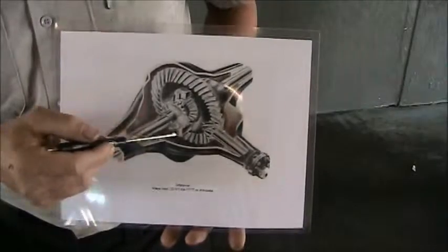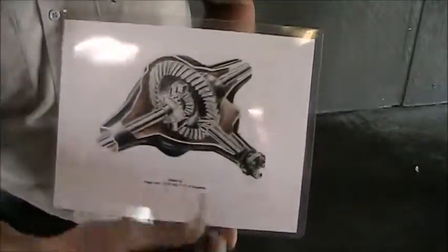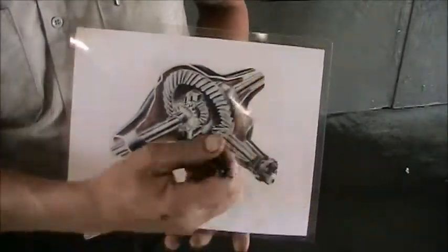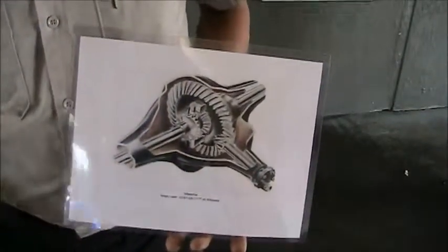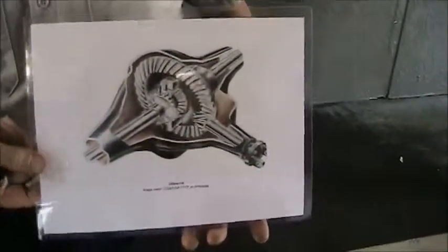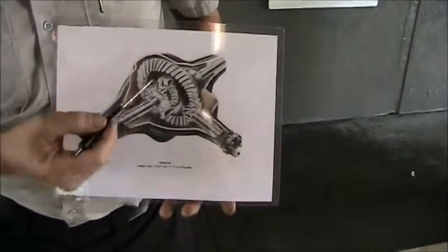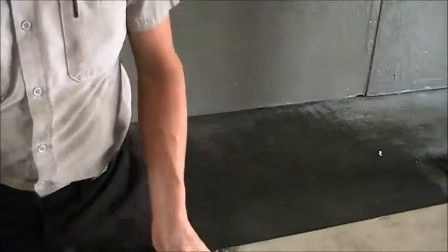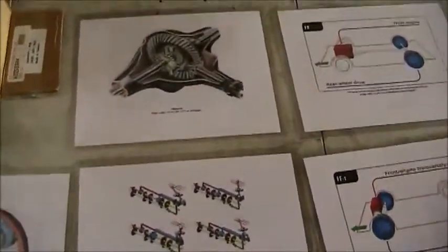Now this other set of gears is called a ring gear and a pinion gear. This is going to convert the rotating energy of the drive shaft input here. It turns it 90 degrees so that we have rotating energy that's going to come out here and go to the tires and transmit that energy to the ground. This is how a differential works in a transaxle. This part of the differential is built into the transmission. On a conventional drivetrain, the differential is separate and it's in the rear of the vehicle.